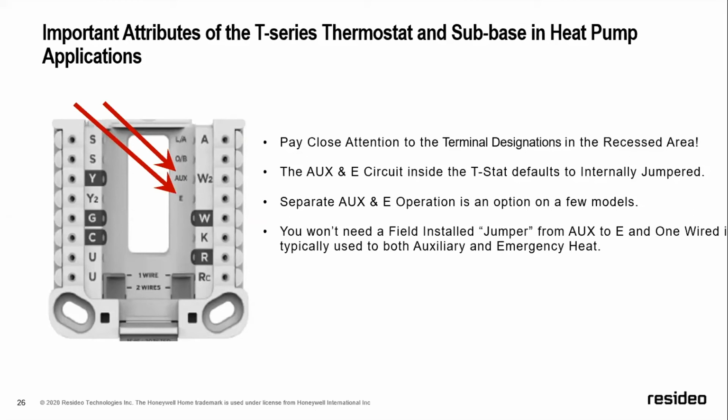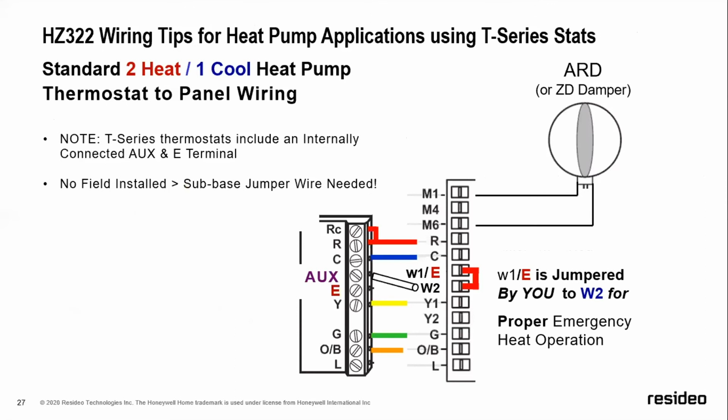But intellectually, I want you to understand that all the thermostats come from the factory jumpered internally in the thermostat. And the reason I mention that is because you don't have a jumper that you need to install in the field like you did in the bad old days when we had separate aux and E terminals on the sub-base. If you'll go to the next slide, please.